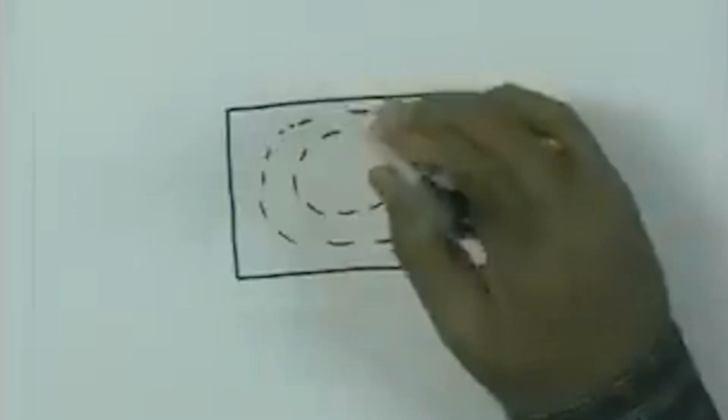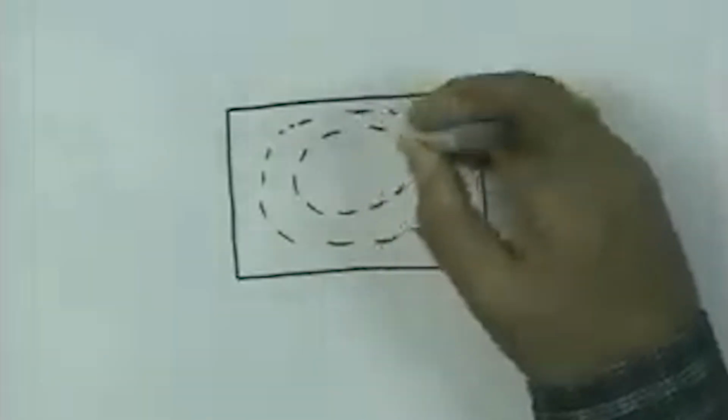If that is so, then we cannot have a displacement current inside this waveguide in this direction. So neither do we have conduction current flowing this way, nor do we have displacement current flowing this way. So there is no current flowing perpendicular to the plane of the paper, and if there is no current, there cannot be magnetic field lines, because by Ampere's law these magnetic field lines must be related to the current enclosed.